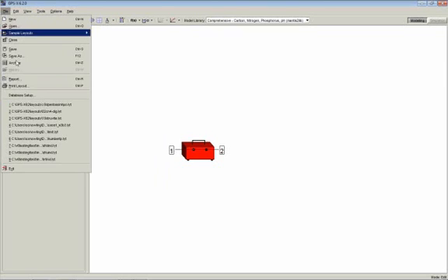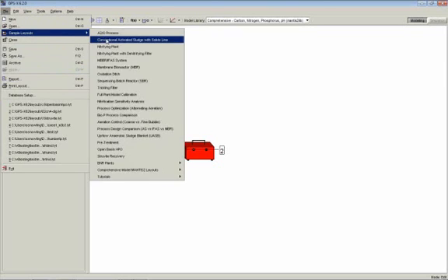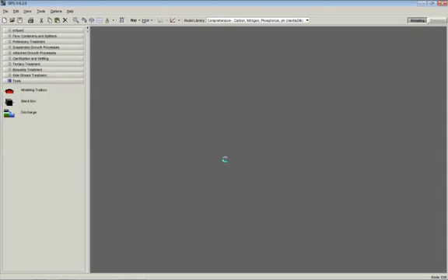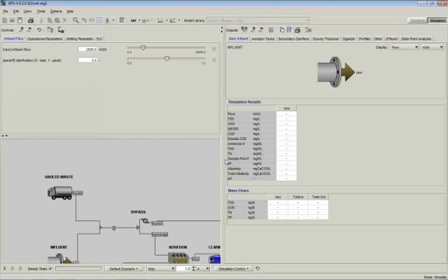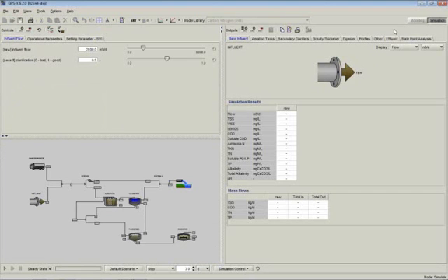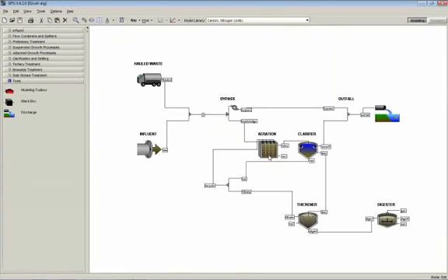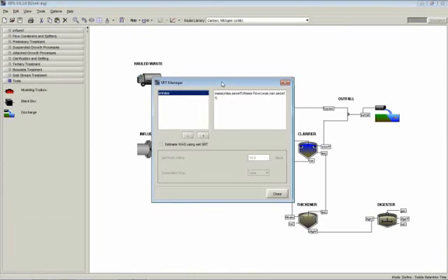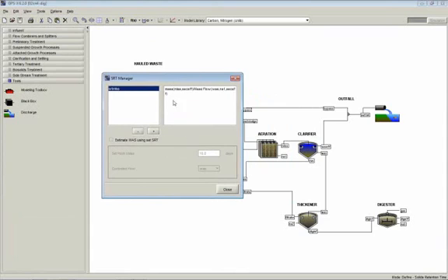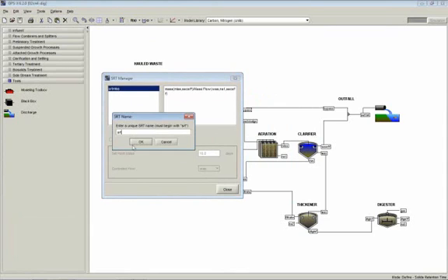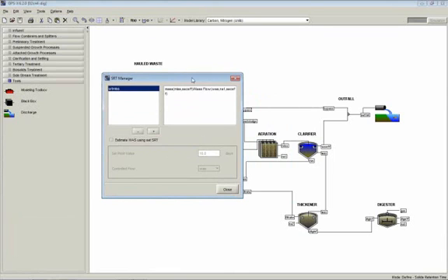And lastly, I will show you very briefly here, going back to our standard carbon and nitrogen removal layout, what our new SRT calculation looks like. So here you can see normally you would come up to our define function, you would select the SRT option and turn define mode on. Now it pops up this new menu where it defines what that equation is, and you can start adding new SRT values if you wanted to have multiple versions within a layout.